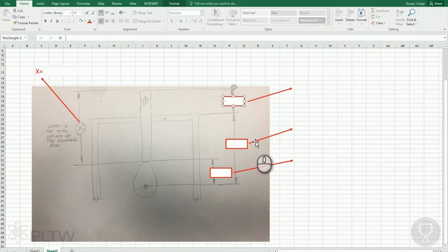So this is a very rough illustration or sketch that I created. We can actually see that this cam is inside the box. The circle is indicating the axle, so we're going to be rotating that axle. The follower rod is coming down through the top of the box, resting on top of the cam. And the one thing that we have to remember is what is the total side distance of your box. So if we were following this with 3.9, we're going to be seeing that that box side is 4.5 inches. We'll just call it 4.5 inches.